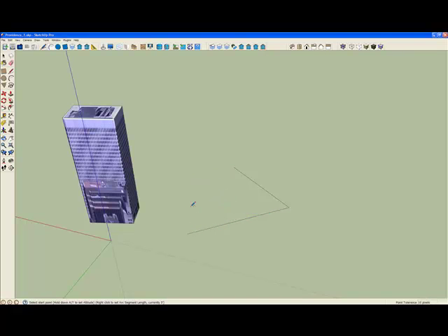Now if I go back and erase that previous line and create a line that isn't parallel, then we may not be able to obtain an arc that's tangent to both, so it'll tell us that it's just tangent to one or the other. So now it's tangent to the arc, and it highlights the adjacent edge that it's tangent to. If we move out further, then it's tangent to the other one, and it works on the other side as well. And there's also doing Control Z, by the way, to move back to other geometry.